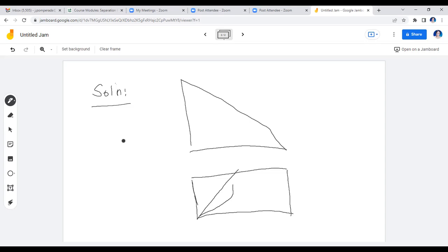Now, in the upper part, you'll have the phase envelope. So you have here your XE or your YA. In here, you have your XC or your YC. In here, you have your XA, the composition of A in the raffinate, so that's XA. In here, you have YA, the composition of A in the extract. Okay? We'll represent V as the extract